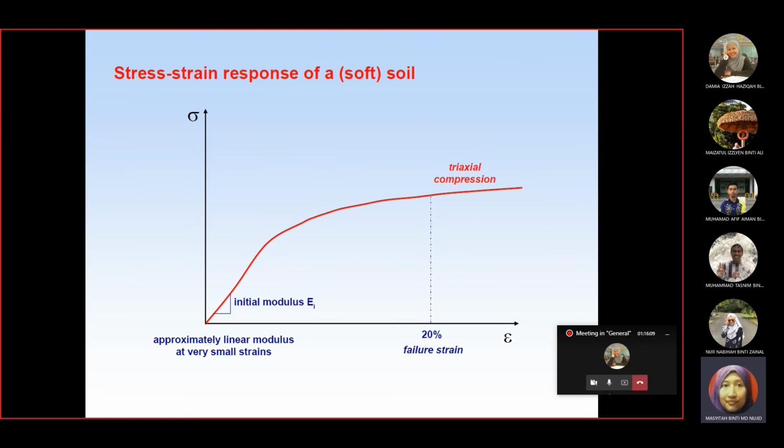That is what it is trying to mention, for example, here. If you conduct one triaxial test, you apply loading until one time there is no indicator that the sample will fail. You can see that the stress increases, the deformation also increases. How long does it take to conduct the test? We can't keep going forever in a test, while the sample is still increasing and the strength is still increasing.